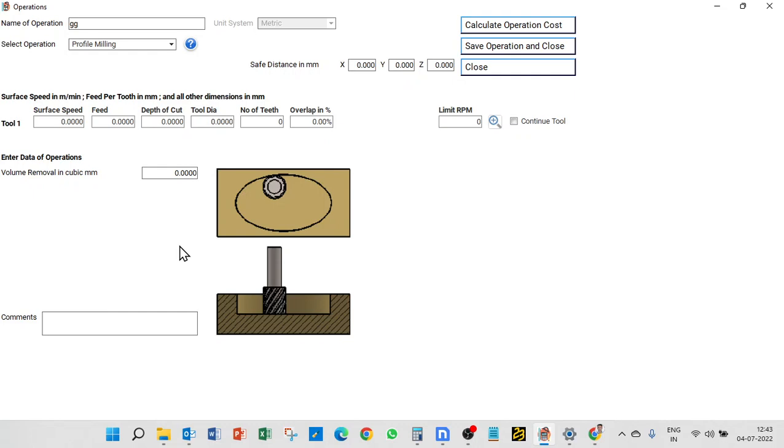This is one of the reasons why most CAD CAM systems fail, because they can give you accurately the length of cut, but they cannot calculate the right timing. It is always approximate. Also, acceleration and deceleration work on each and every movement you do. How your CNC behaves to all the information it collects also plays an important role. Probably we will write a blog on this someday. So profile milling is working on material removal rate, MRR.